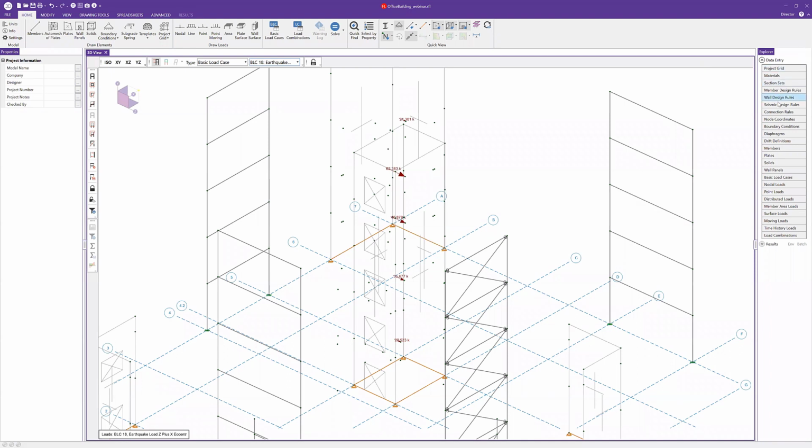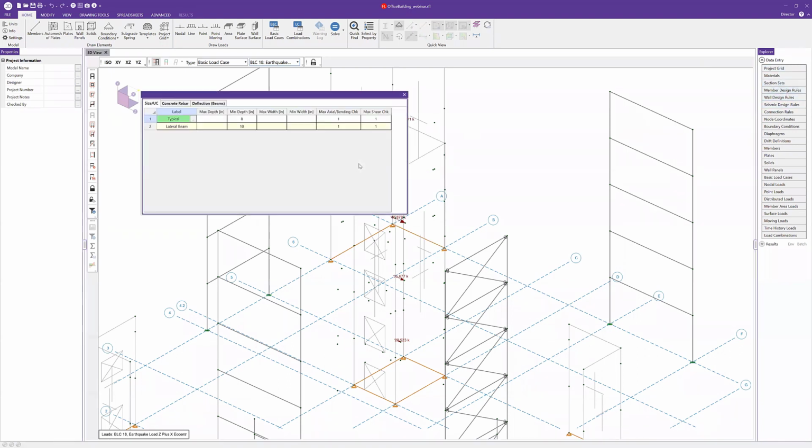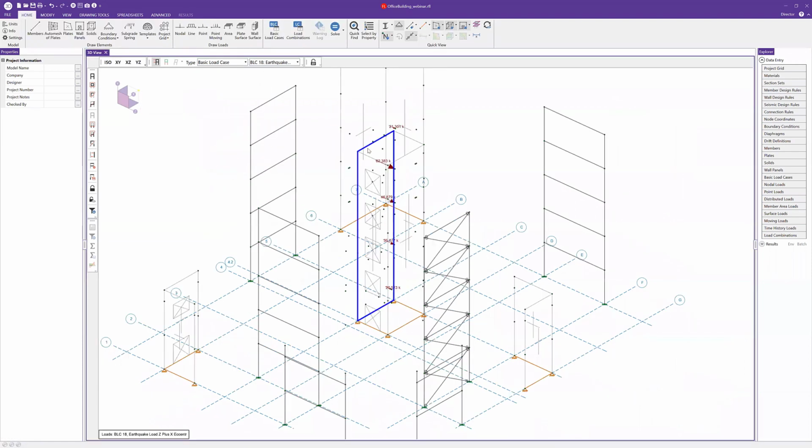We also have our design rules. If I look at our member design rules, those member design rules are transferred in from RISAFloor. So really, the different programs are being used to model and evaluate the same structure. They're carrying through loads and design criteria, and it's really just allowing you to look specifically at the part of the model that you want to focus on in that particular software. Whether it's gravity analysis and modeling in RISAFloor, or lateral design and other specialty elements in RISA-3D, or foundations, connections, it doesn't matter. It's just giving you a smaller window to focus your view to make sure that you get exactly what you want in that particular model. And so those design rules are coming across as well.